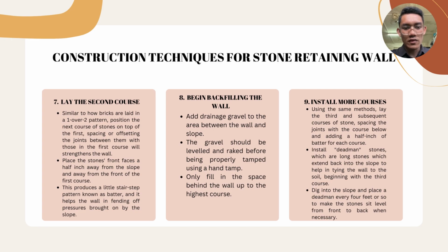Place the stones' front faces a half-inch away from the front of the first course, toward the slope. This produces a little stair-step pattern known as batter, and it helps the wall in fending off pressures brought on by the slope. Number 8 is begin backfilling the wall.